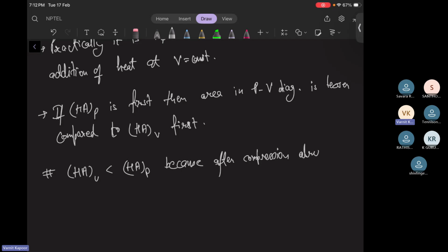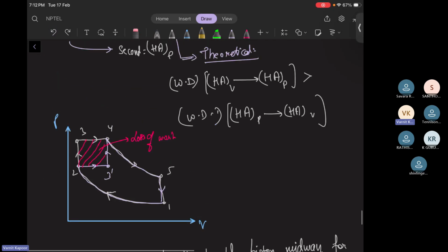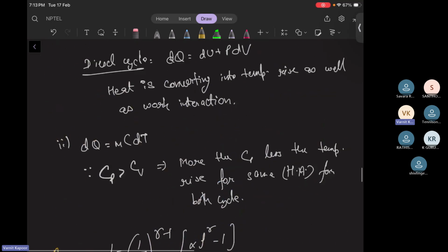already the pressure inside the cylinder is high. Okay. So when I'm saying that if I add first 2 to 3 heat addition at constant volume, then already the pressure is quite high. Okay. And then at same pressure, I provide the heat. But if I do heat addition at constant pressure first, then temperature will eventually rise. We have seen from the TS plot here.